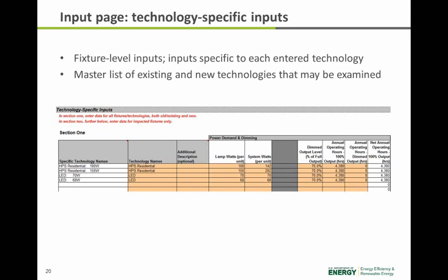One of the attendees recently asked for additional discussion on calculating LER, or luminaire efficacy rating, for an HID product versus luminaire efficacy. For an incumbent technology, it all stems from how the products are measured. It's the luminaire efficiency, think of that as the fixture efficiency, the amount of light that actually leaves the fixture, times the total or nominal lamp lumens. If you've got one lamp, it has a nominal light output. If you've got multiple lamps, you would enter that in there.